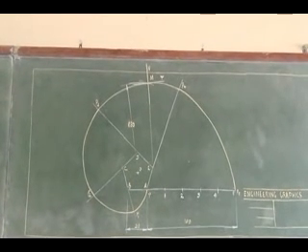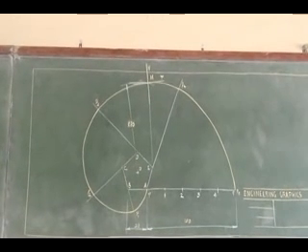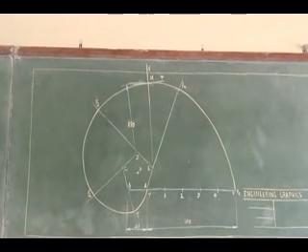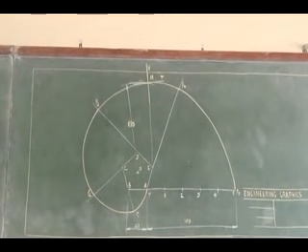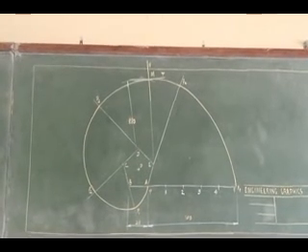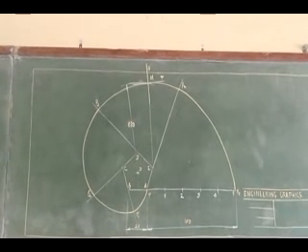Right. To draw the tangent and normal for the given problem of the pentagon, mark the point M on the involute, measuring 80 mm from the center of the pentagon. The point will be obtained between the segments P3 and P4, nearer to P4. From M, connect M to the center of the involute segment P3, P4.